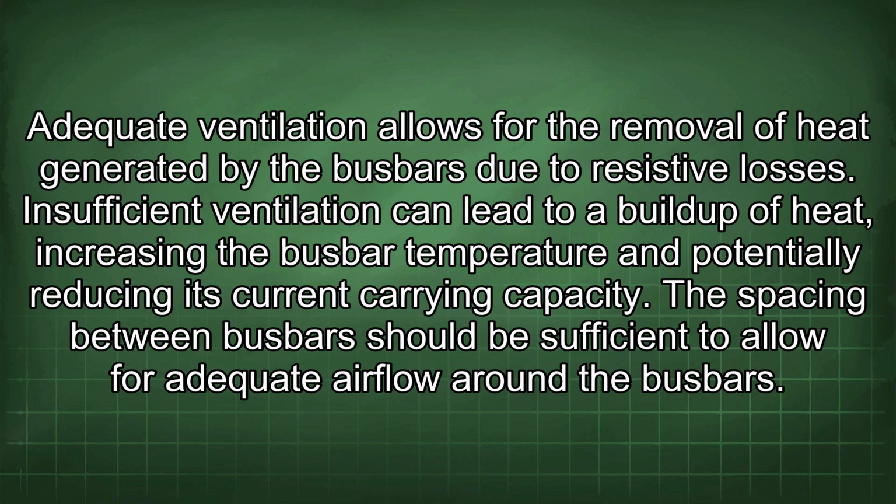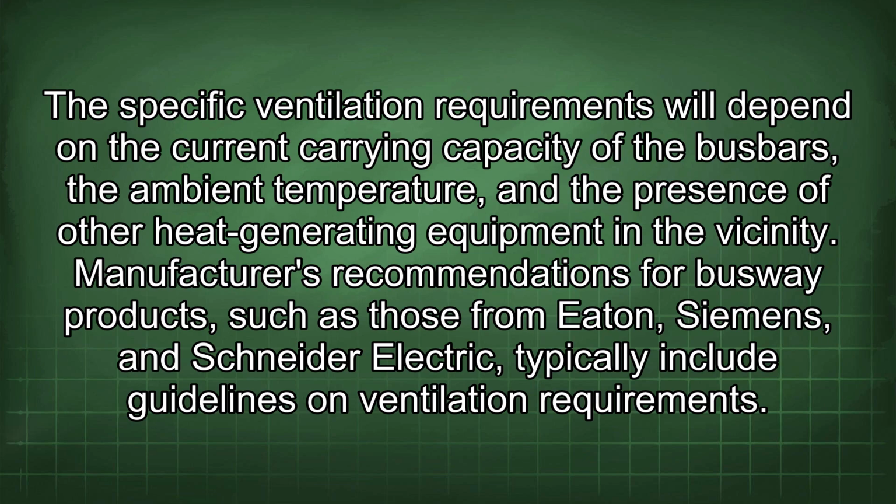The spacing between busbars should be sufficient to allow for adequate airflow around the busbars. The specific ventilation requirements will depend on the current carrying capacity of the busbars, the ambient temperature, and the presence of other heat-generating equipment in the vicinity. Manufacturers' recommendations for busway products, such as those from Eaton, Siemens, and Schneider Electric, typically include guidelines on ventilation requirements.